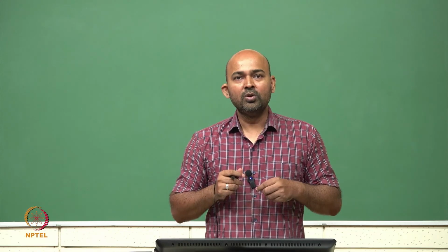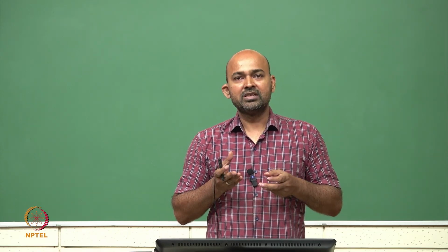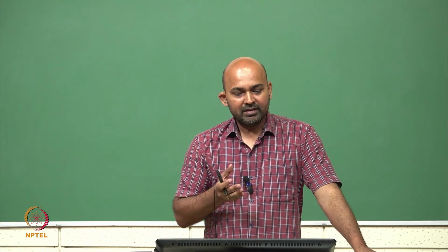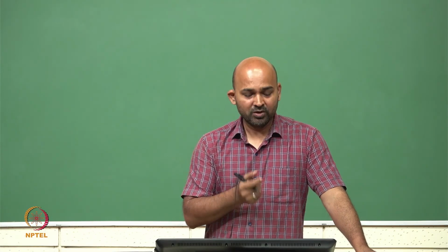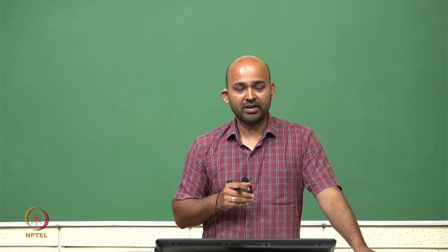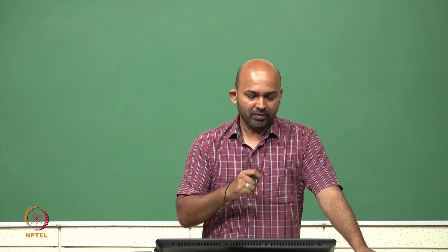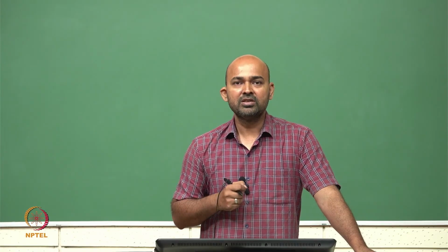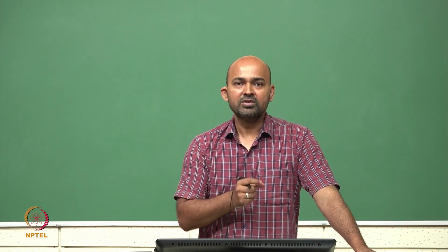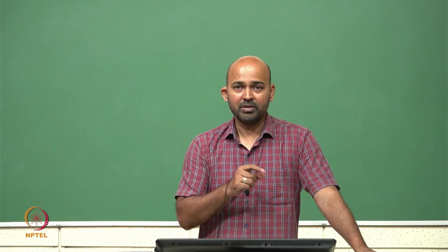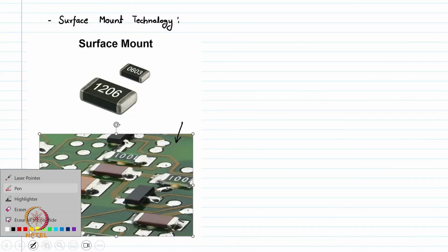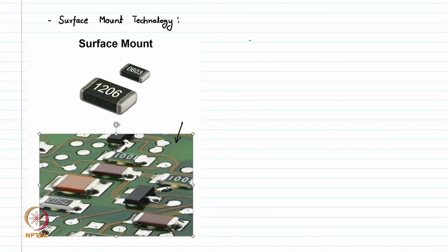If we are not drilling holes, we can design the circuit such that half of the circuit is on one side and half is on the other side of the PCB, and we can mount on both sides. They can have a very high switching speed because they are very small, so the parasitic effects are very small. The only problem with SMD components is that they cannot handle as much heat as PTH components can. That is because the size of these components is very small compared to PTH components.